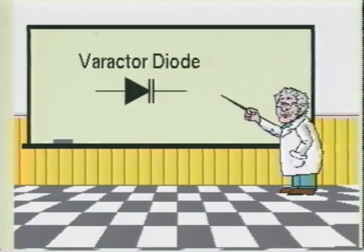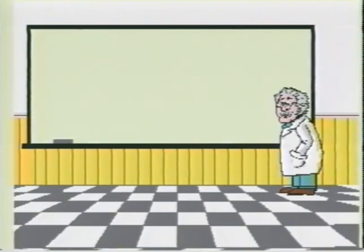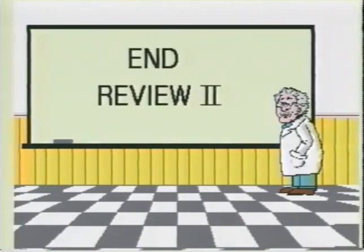The varactor diode is used as a voltage variable capacitor. Varactors are normally operated in the reverse bias mode, and its capacitance is that of the depletion region. This completes review number 2. Next we shall examine some common amplifying and switching devices.